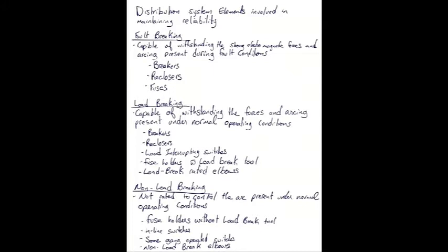So these classes of assets, they're really not designed to break load at all, right? So you have to break your load elsewhere, and then you can switch with these. So they're still used for circuit segmentation, but they're not used for load breaking.